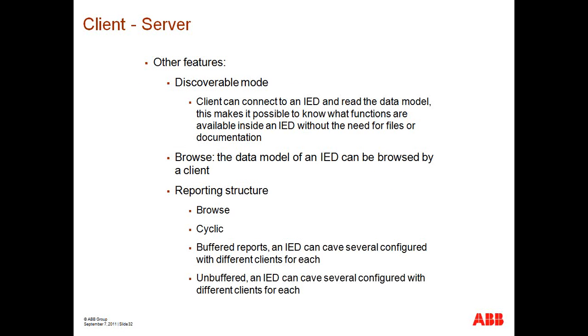From a protocol perspective, there are some additional features worth mentioning. Discoverable mode: essentially, IEDs supporting 61850 allow clients, devices that would like to read information from an IED, to connect with nothing other than its IP address and get all the information it has available, its data model.